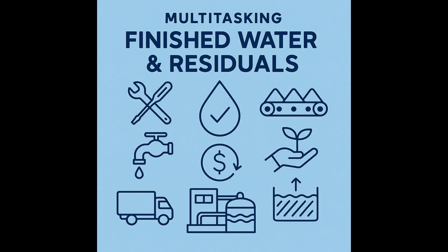Given all that complexity, especially PFAS, what's the operational playbook for making land application work reliably for, say, a 10 to 20 MGD plant? Okay, a practical playbook would look something like this. 1. Characterize and test first. Do thorough bench or pilot testing for dewatering performance. Critically, conduct PFAS screening if there's any reason to suspect it might be present. Discuss testing protocols with DEQ and align with EPA guidance. Know your residuals inside and out before you plan application.